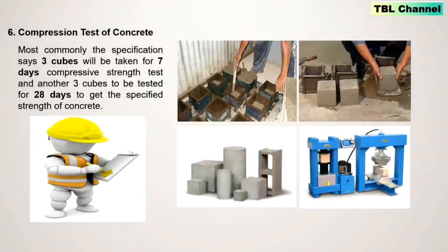Number 6. The compression test of concrete. Most commonly, the specification says 3 cubes will be taken for 7 days compressive strength test, and another 3 cubes to be tested for 28 days to get the specified strength of concrete.